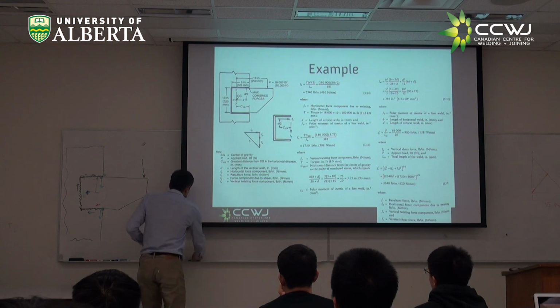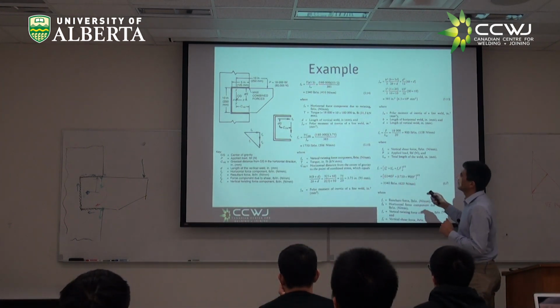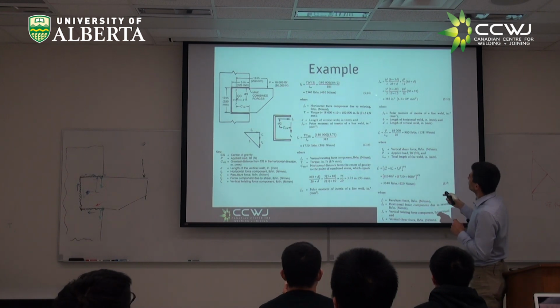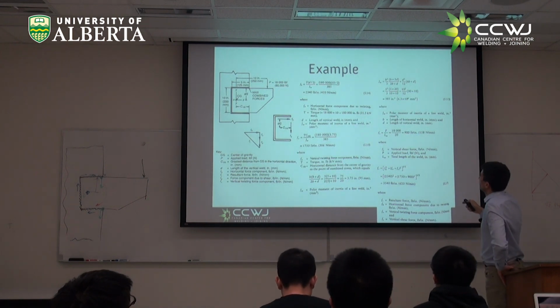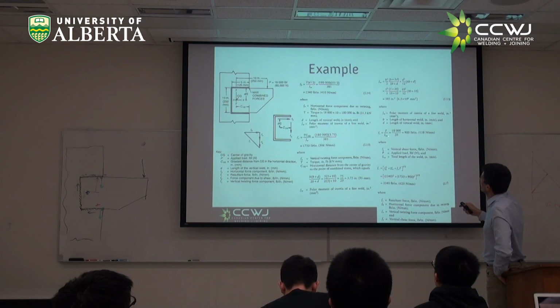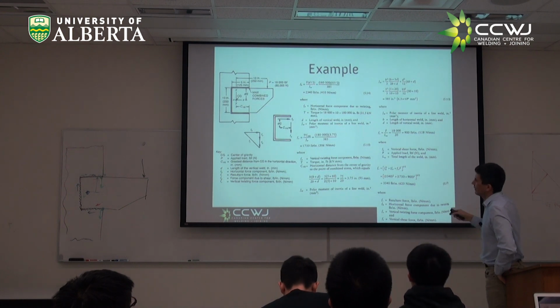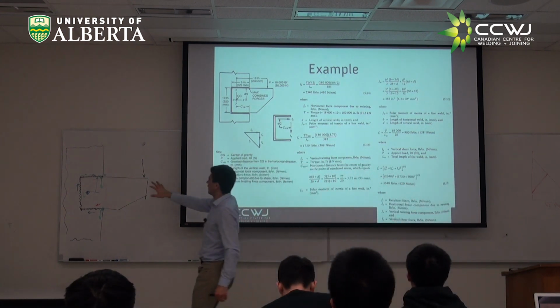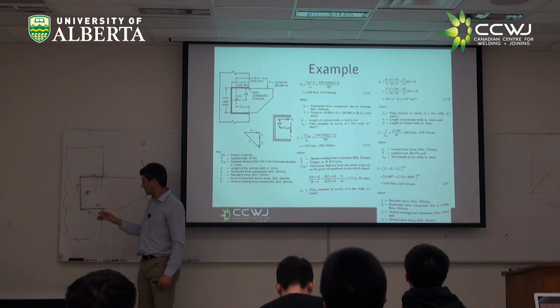All right. And in addition to either of those two, we have the force from the shear. The force from the shear, we decided, is force divided by the whole length of the weld, and that is applied evenly all over the place. Okay?